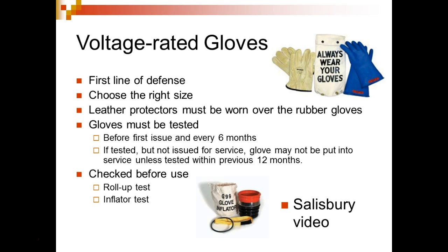So that's what's strange. Single voltage motors usually are supposed to have an overload inside the motor. If they don't have an overload inside the motor, then they're supposed to have an external overload. So what was happening is you were hearing that motor try to pull starting current, and the fuses are not going to what? The fuses or the circuit breakers are not going to pop because they had to be rated to allow the motor to start in the first place. So motors are supposed to be overload protected. Anything above, good gracious, it's like a third of a horsepower, they're supposed to be overload protected, either internally or externally.